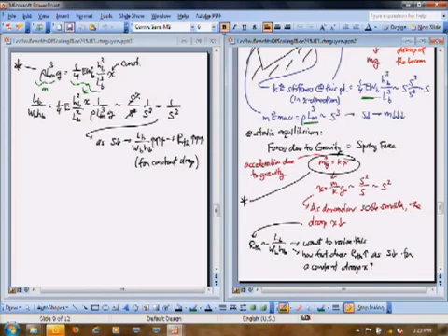Yeah, so what you're seeing, that's the other part of the scaling thing. So CTH goes down faster than RTH goes up, is what's happening here. So it's the cube thing that CTH depends on, and RTH doesn't depend on the cube. RTH depends on 1 over S, whereas the thermal capacitance goes as S cubed. So there's a square law difference. As you shrink things down, thermal capacitance goes down much quicker than RTH goes up. So that's why your thermal time constant drops very fast.